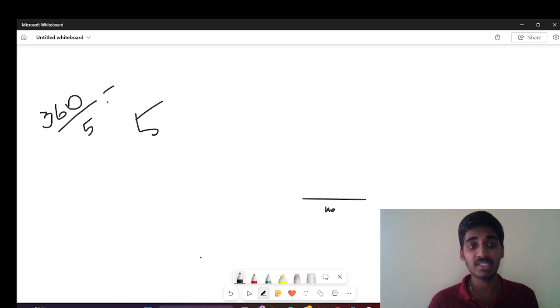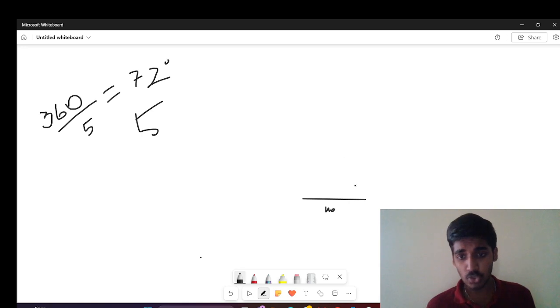We'll get 72. Means we should divide 360 by 5, as the pentagon has 5 sides, and we'll get 72 degrees. So let's measure 72 degrees over here.